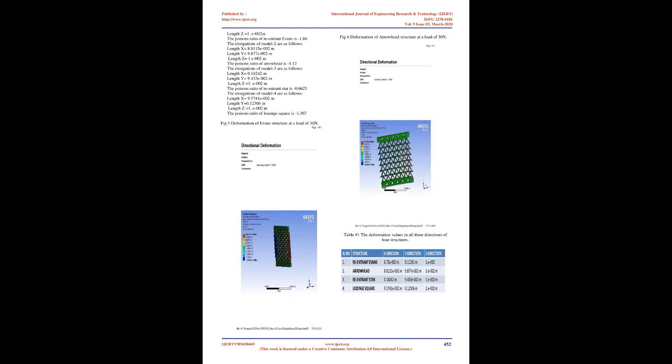Despite these advantages, they have difficulties in manufacturing due to complex design, which limits their applications. Many reports are focused on theoretical and material response. Different types of NPR structures have also been developed. These are categorized into several types such as chiral, reentrant, rotating and honeycomb, and others. They found that 2D chiral and 3D geometries have the highest negative Poisson's ratio and the 3D pyramid has the lowest.